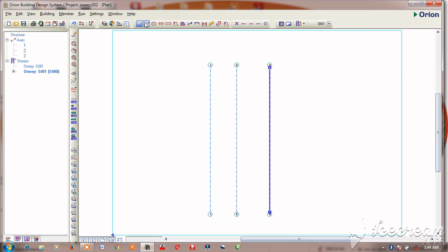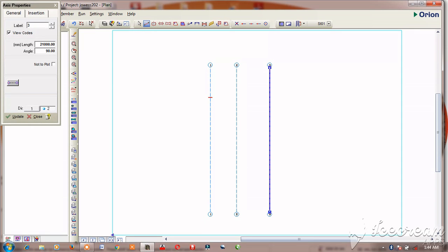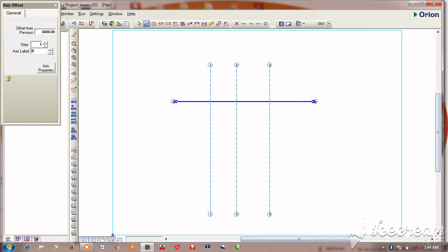Now for the x-axis, close it here. Then come to the axis again. I want to do it for the horizontal. Click the control key, then release your hand. The next thing is to offset. What is your offset distance? My offset here is 3825. Then click it here. It has generated.